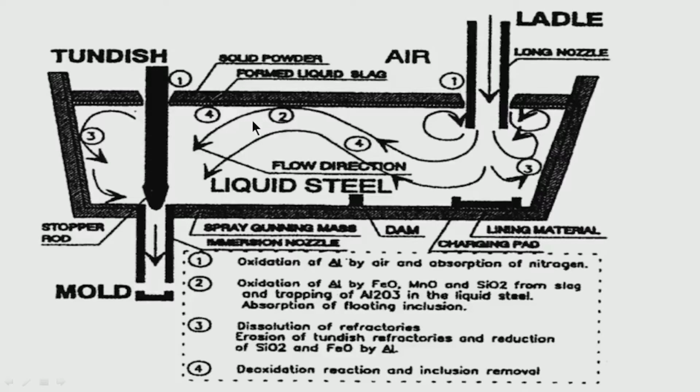So, this is called increasing the residence time of liquid steel in the tundish. So, the flow control devices have some role, dams and weirs. Moreover, I had mentioned the liquid steel should not be allowed to impinge directly at the bottom of the tundish.